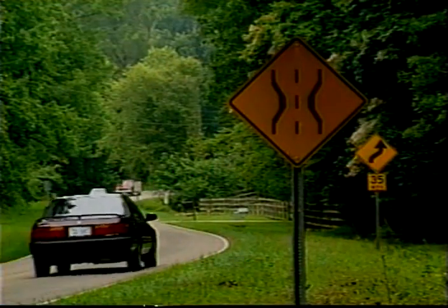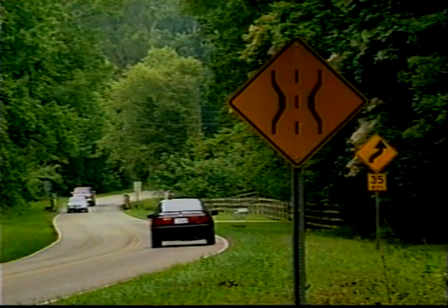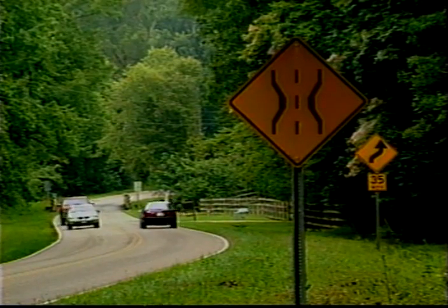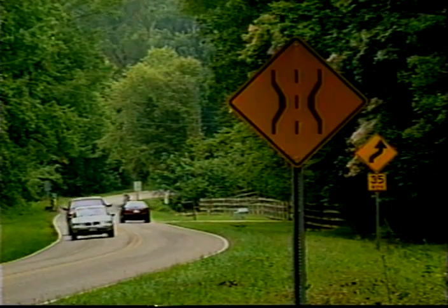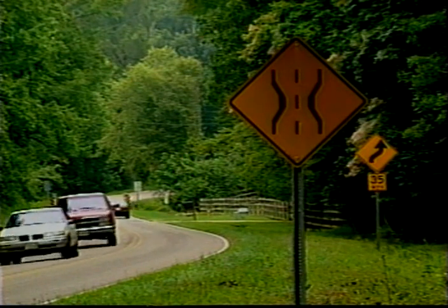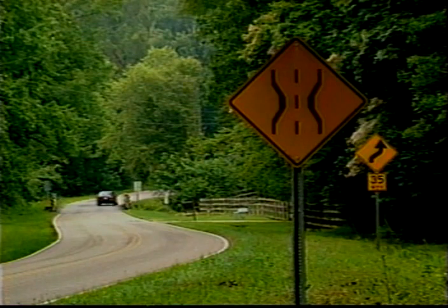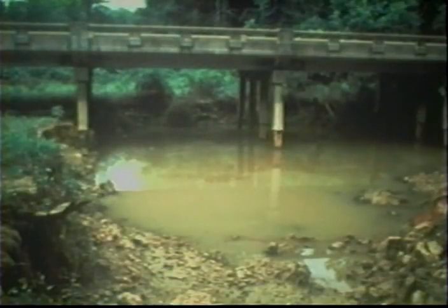Deficiencies in deck width or approach roadway alignment may cause accidents. Since load and geometric deficiencies can be a hazard, signs should be posted well in advance to notify motorists that they are approaching a deficient bridge. Waterway deficiencies can result in constriction of water flow, causing flooding or possibly erosion of soil-supporting bridge foundations. Waterway deficiencies may also hamper navigation in larger channels.